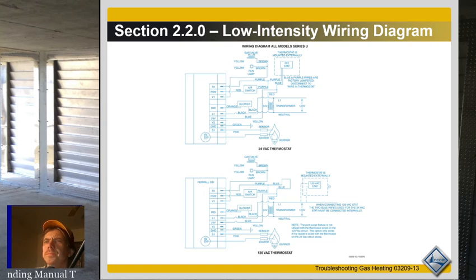So on something like this, we got 120 volts coming in, transformer, powers the blower over there. We got flame sensor and ground. The igniter. Usually, I'm trying to think. Yeah, I think pretty much all the ones I've seen, it's pretty common on spark ignition.